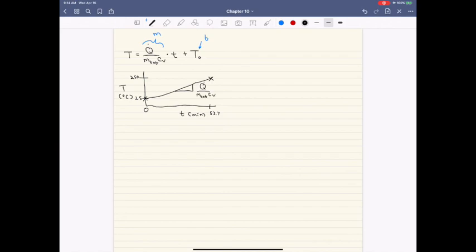And really, the last thing I want to point out here is if you knew, for instance, the total mass of your system, and you also knew the heat rate that you applied to your system, you could use those pieces of information and also the change in temperature to figure out what your average heat capacity of your system was. And so this is actually how people solved or measured the heat capacity of various chemical species. This is the sort of experiment that they would do.